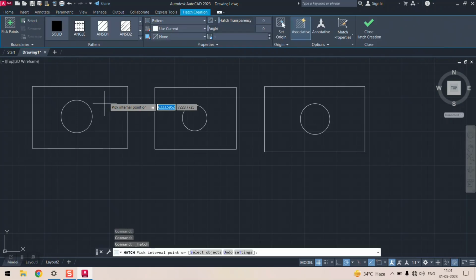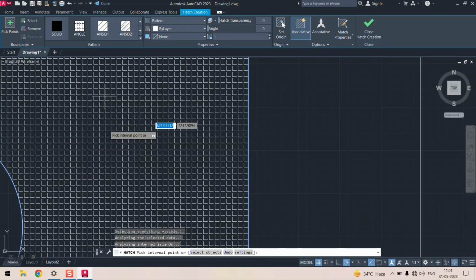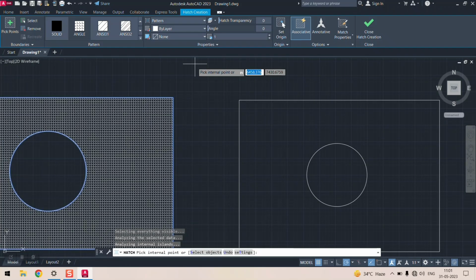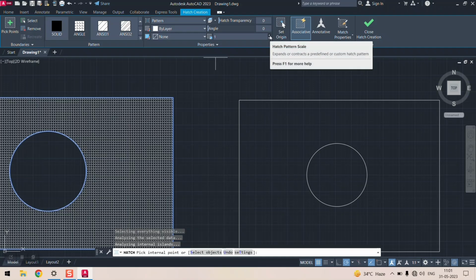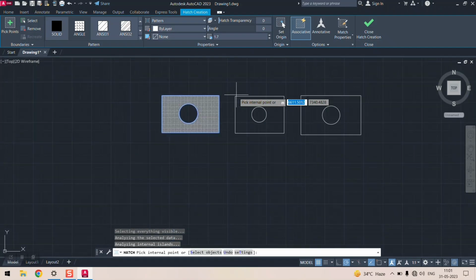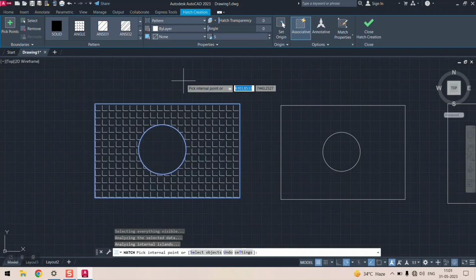So first, if I use the hatch, it will give me a few options, like if I want to give the angle one, let us suppose I am choosing this first angle. See, you can bring an artistic appearance to your CAD drawing. The more you increase, like let us suppose if you make it a 5, it will increase the gap between the small tiles.